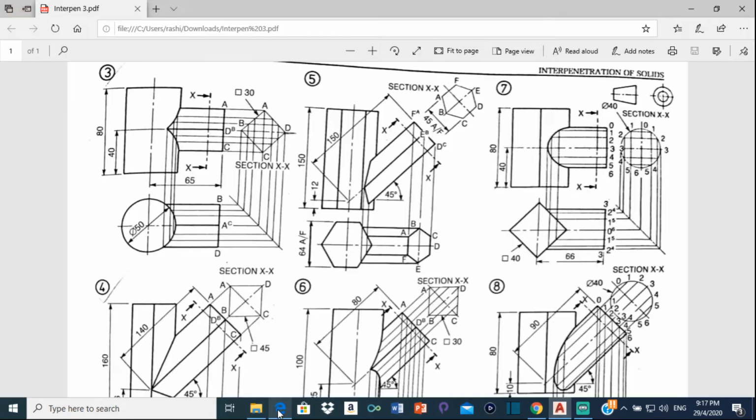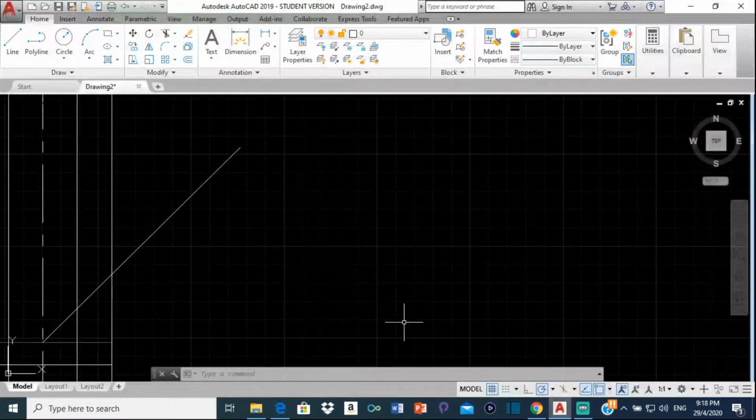The next thing on the drawing, it says that this distance right here across the flats is 45. So if this distance is 45, that means that half of that 45 would be 22.5. And that's the decimal measurement that we're going to be using in this drawing, which is why I set the units to 0.0.